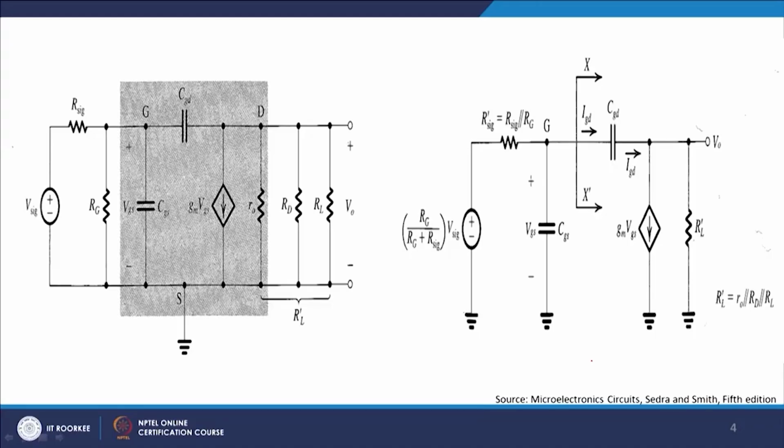With this knowledge, let me do a mathematical treatment for the high signal frequency and low frequency response. So, if you look here clearly at the high frequency component, if you remember from the previous slide, I have just replaced the MOS device with its equivalent circuit model, the pi model.